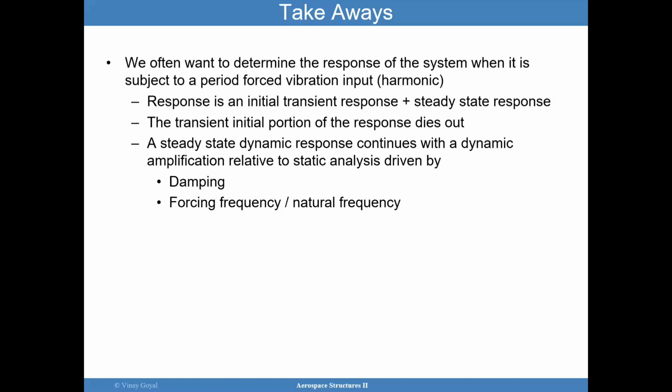We've also demonstrated that if the forcing frequency is significantly smaller than the natural frequency, then the amplitude can be predicted just by doing a simple static analysis. In addition to that, we demonstrated that if the forcing frequency is significantly higher than the natural frequency, you can put a lot of energy in, you can try to vibrate this system a lot, but perhaps the system will not respond to it as much as you would have thought.